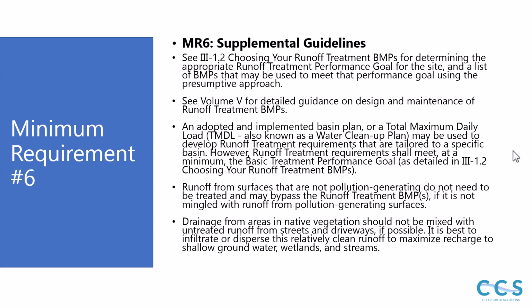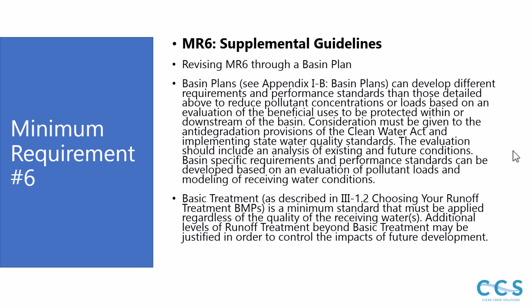Drainage from areas and native vegetation should not be mixed with untreated runoff from streets and driveways if possible. It is best to infiltrate or disperse this relatively clean runoff to maximize recharge to shallow groundwater, wetlands, and streams. So, revising MR6 through a basin plan.